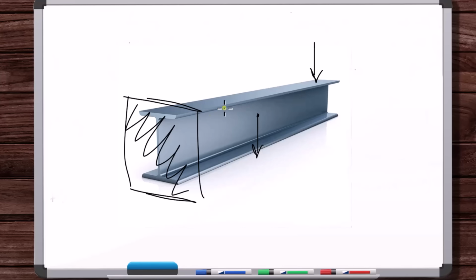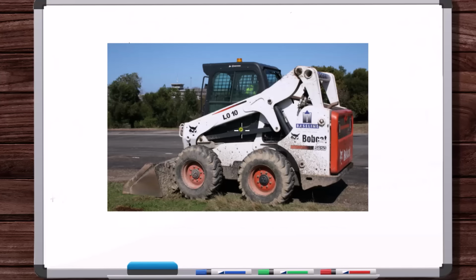Okay, now it's important to understand this definition of internal forces, when they cancel each other out in a free body diagram and you don't put them, because, okay, I've mentioned several times that to do a free body diagram, you can bring, like let's say from this Bobcat, you could bring one single component into empty space, or two or more connected components. Let's think about the idea of two or more connected components. Let's say we're going to bring this entire piece, it looks like two connected pieces, into empty space.